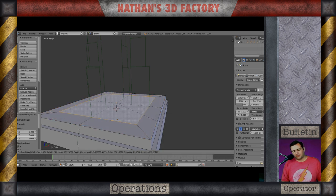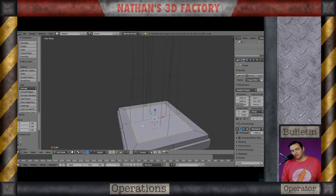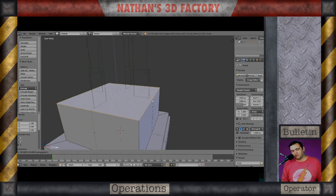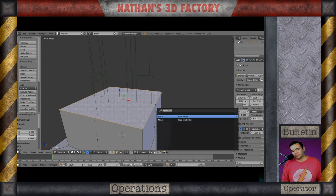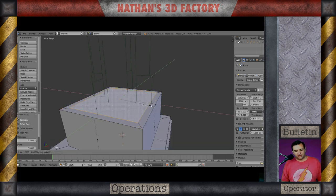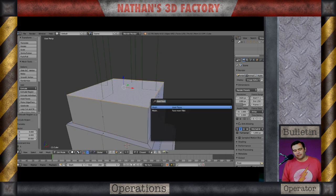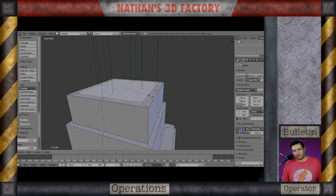So I extruded upward on that, and I'm going to inset there, and then I'm going to scale, not including the Z-axis as I'm doing that scaling, and then once I get that scaled, I'm extruding upward. I'll extrude upward, scale inward, and inset. Okay, I'll keep going for that.